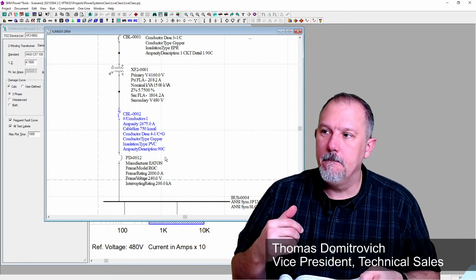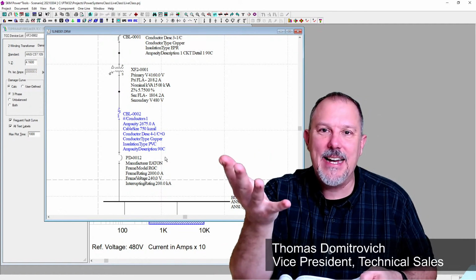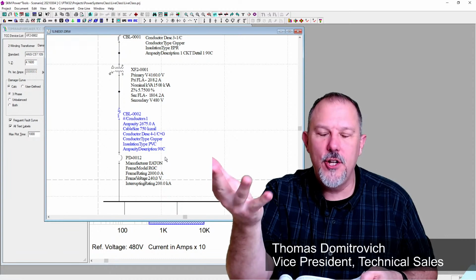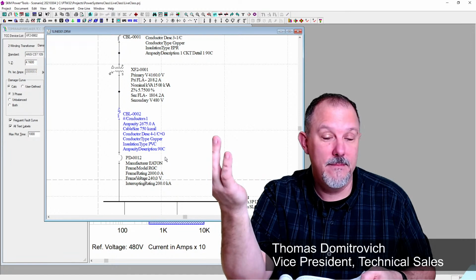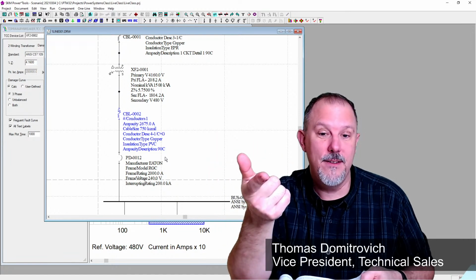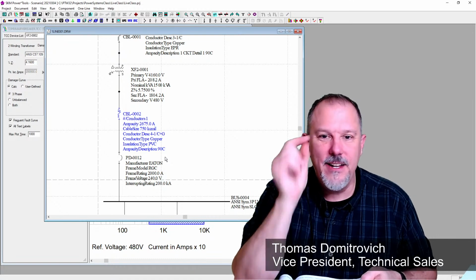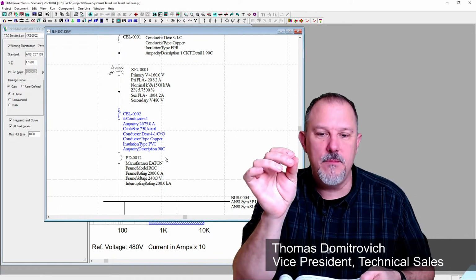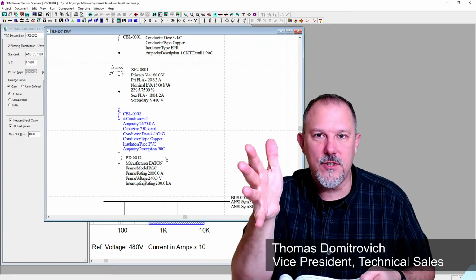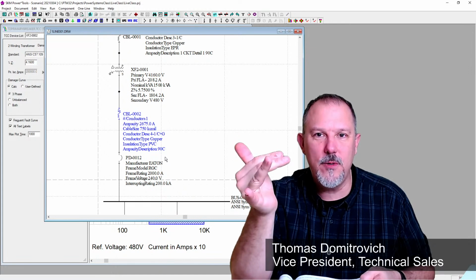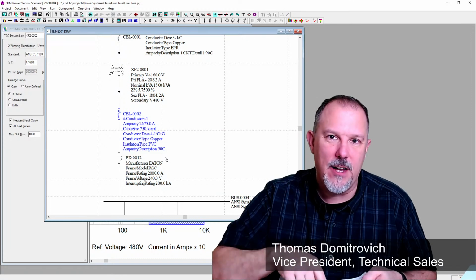I have 5 conductors. Can I put 3 raceways, 2 conductors in one, 2 conductors in another, and 1 in another? There's a question for you. Robert from Omaha, Ryan Jackson, Nihad El Sharif, James Smith: I want to take 5 conductors, put 2 in one raceway, 2 in another raceway, 1 in another raceway. Is that permitted by the National Electrical Code?